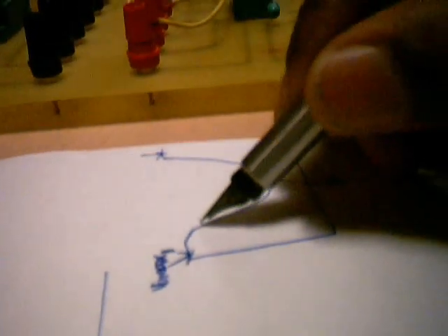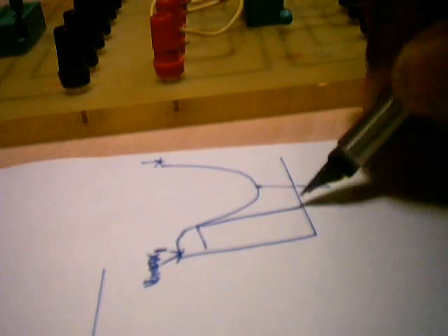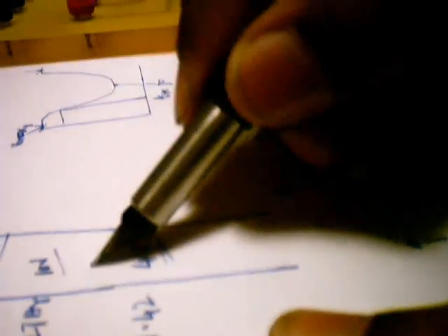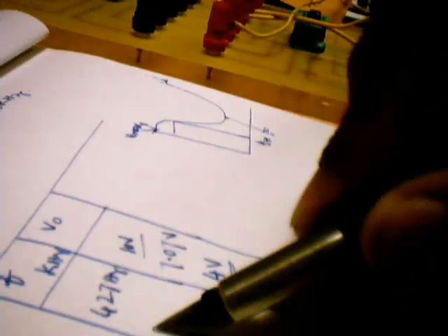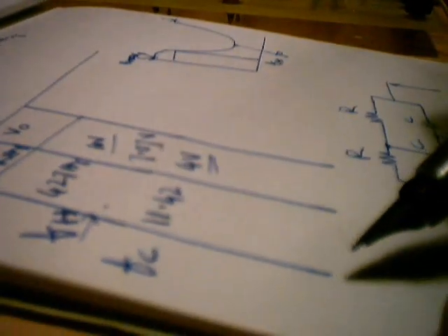Okay, you can find the frequency which is 0.707 times of that, which gives the higher cutoff frequency FH. So that you can know from this. So what is 0.707 of this? So you need to get a voltage corresponding to 0.707 of that. You find what is that frequency. So that frequency at which you get this output amplitude, keeping the input voltage 12 volts, happens to be the higher cutoff frequency. Do the same thing on the other side of your FC.